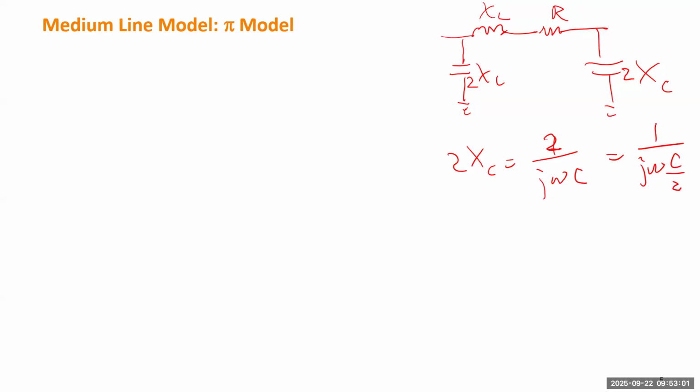So the total capacitance to the ground is C. You either use C as a single capacitive element and put it on the left or the right, but either one will introduce some error on the other side. Or you split it in half. The total C is split into halves, so use each one to calculate the reactance, which will give you double the reactance of the original one. Then you give this one to each side.